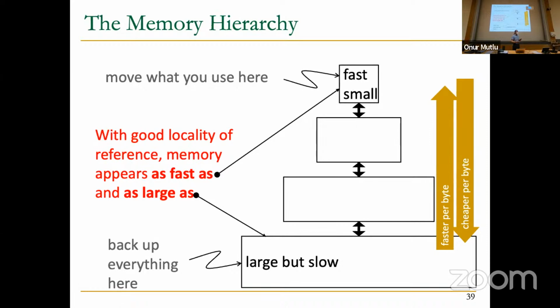And we normally consider registers as part of the memory hierarchy as well. In fact, if you remember lecture 9, when we introduced the registers as part of the von Neumann model, we said that these are fast temporary storage. The reason we have them is that memory access is too long. So why not have a register file that is close to the arithmetic logic unit, such that you can store the temporary variables that you need often or soon, so that you can access them faster. We call this the locality of reference, right? You need that locality of reference, and we're going to exploit essentially the same thing. So registers are really part of your memory hierarchy, except they're managed in a different way, as we will see.